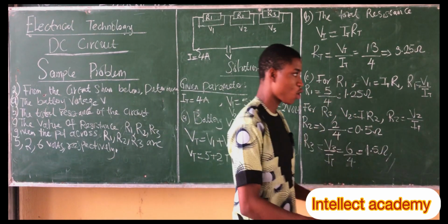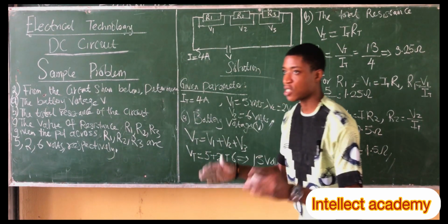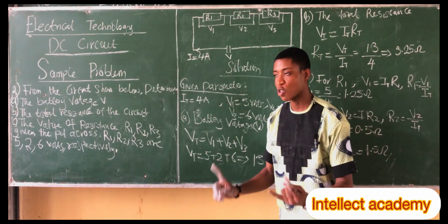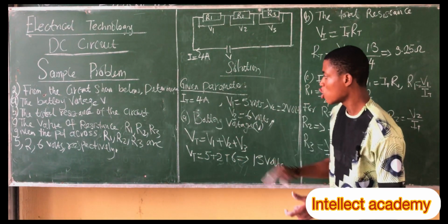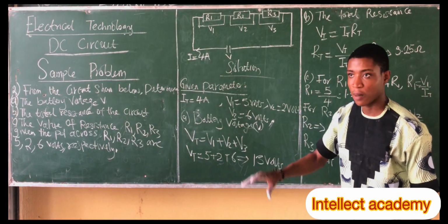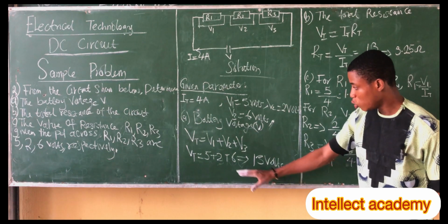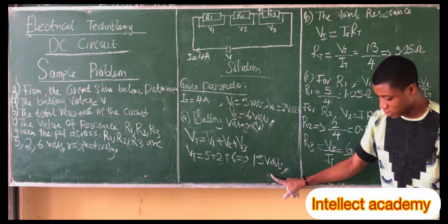So therefore, this is the concept when solving an equation like this, where the resistances are unknown. The small trick is that they give us the total current and they give us the voltage of the individual resistors. The concept is easy. You calculate the total battery voltage, which is the sum of the individual voltages of the resistors. We did that by adding them. We have 5 plus 2 plus 6.